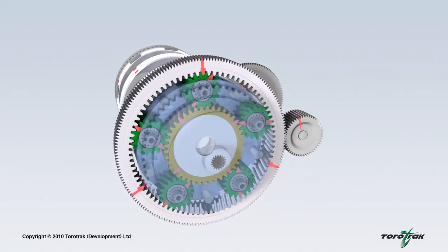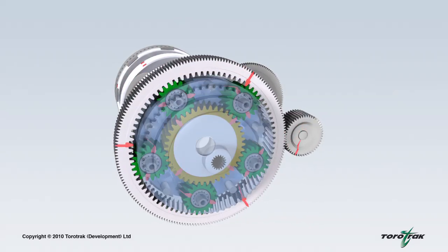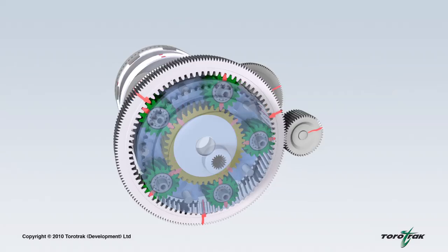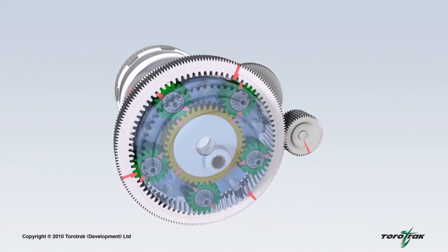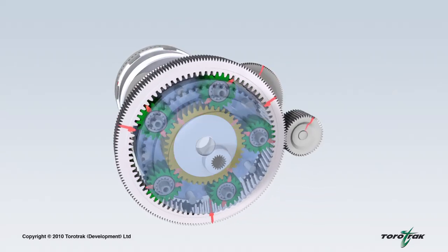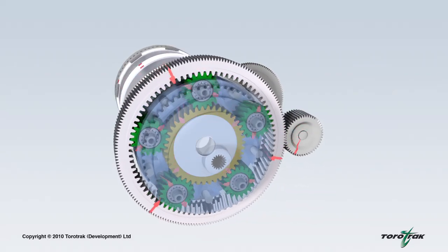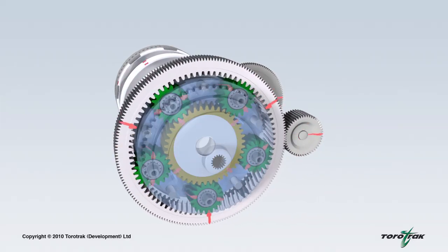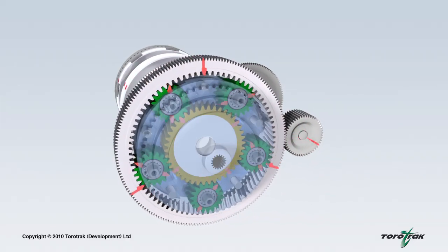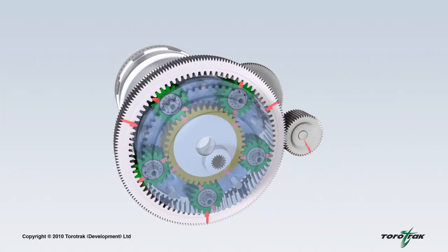The epicyclic gear train acts as a mechanical calculator. It subtracts the engine speed, at the sun gear, from the variator output speed, at the annulus. If the answer to the calculation of the difference between the engine speed and variator output speed is 0, then the transmission output is stationary. This condition is termed geared neutral.